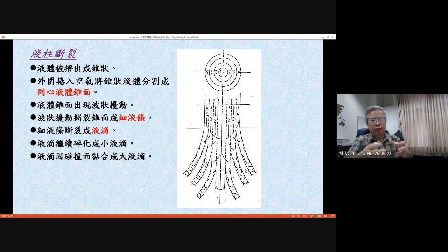A liquid current is different from the previous small liquid jet. A liquid current means they have a large cross section. That means the liquid velocity on a given cross section of a liquid jet is different. Those velocity differences will tear your liquid into different layers. When they are coming out of the exit plane of the jet, they will tear into different layers of a liquid spread.